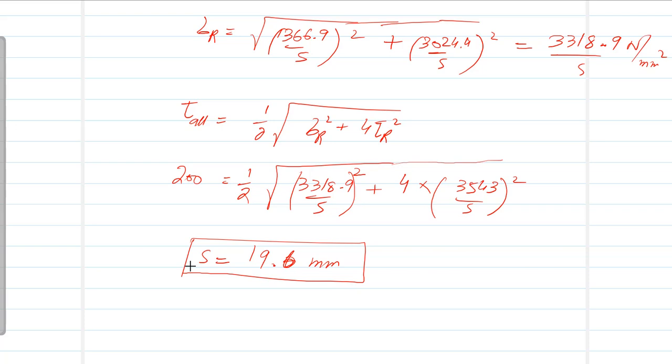It could be there are two loads. One could be horizontal, one could be vertical. There could be an angle at a certain angle, as we have seen. So the important thing is to try to understand those problems, understand the geometry of the problem, and understand how to perform a vector sum. If the stresses are in the same direction, just directly sum them together. If they are at a certain angle, or at 90 degrees, just take the resultant, which is found by using the Pythagoras theorem.